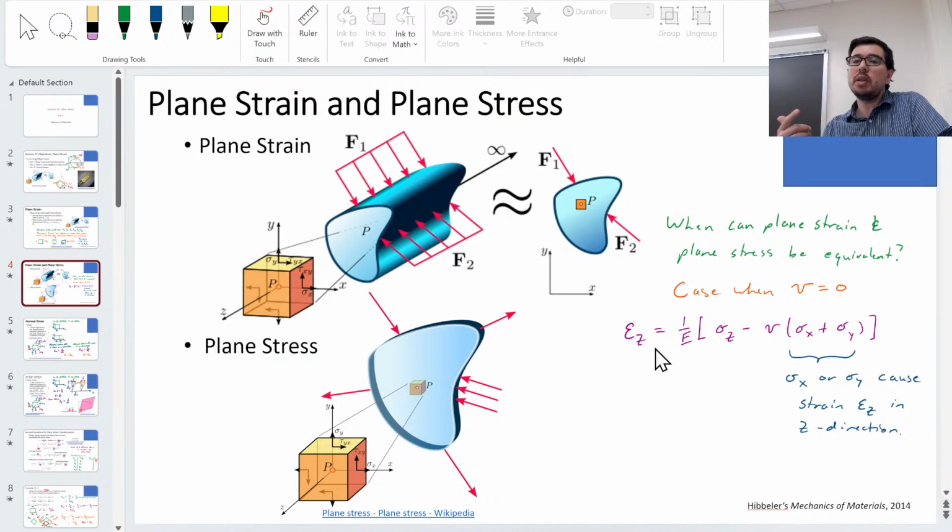And when we were doing it with the stresses by themselves, we don't think too much about the Poisson ratio. That's not completely true, because we have tau equal to G gamma, okay? And G, the shear modulus, has dependence on the Poisson ratio. We've just been given that, right? We said G is equal to E over quantity 2 times quantity 1 plus nu. That actually comes up again in this session. But something to keep in mind is that when we're looking at just the normal strains, we do have this dependence on stresses in the orthogonal directions, through the Poisson ratio.